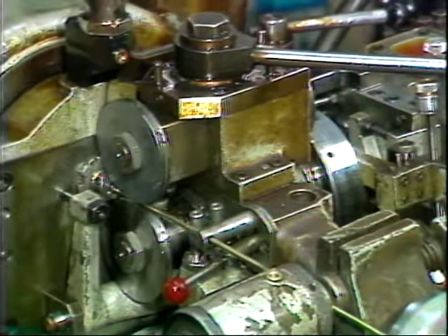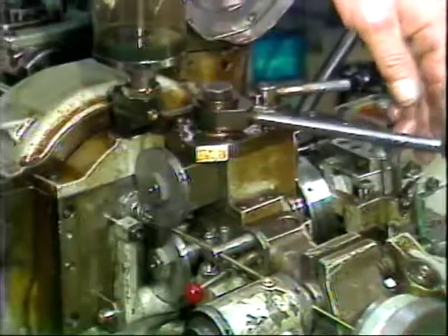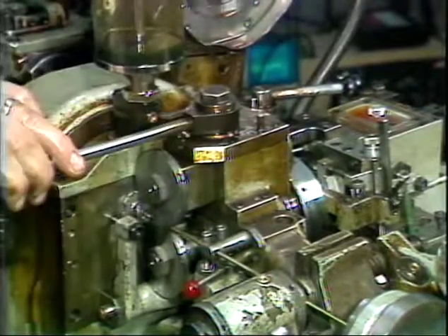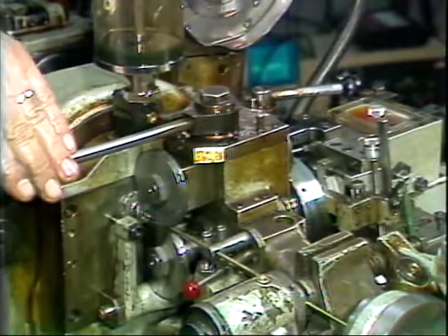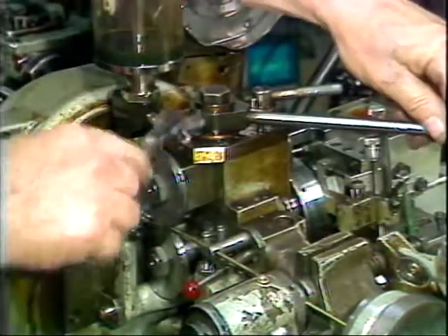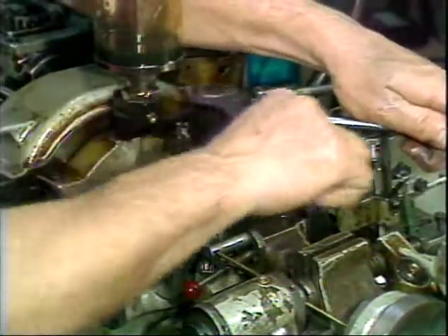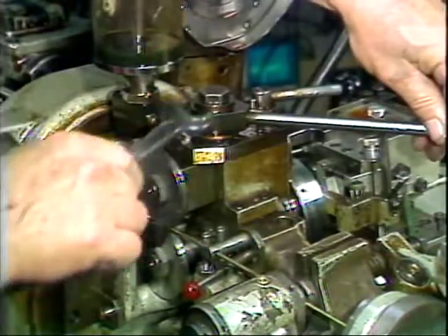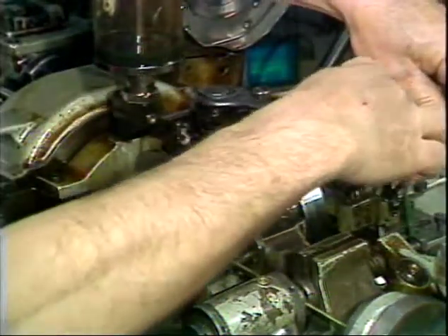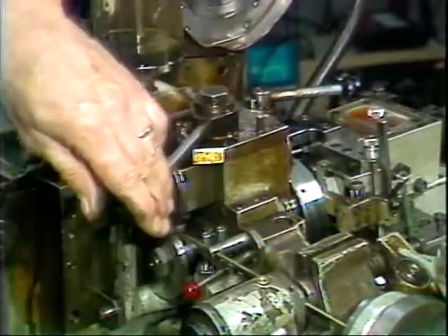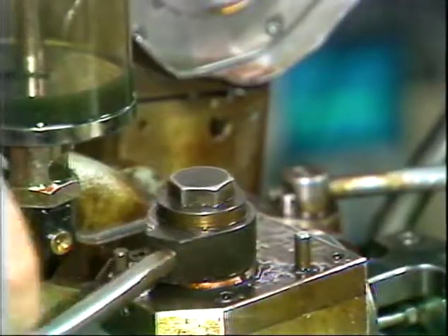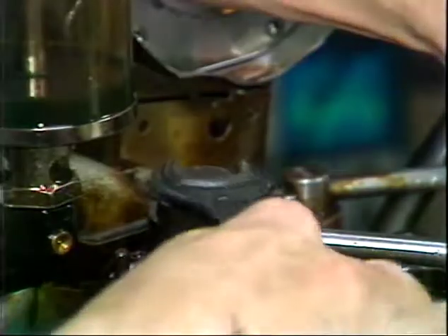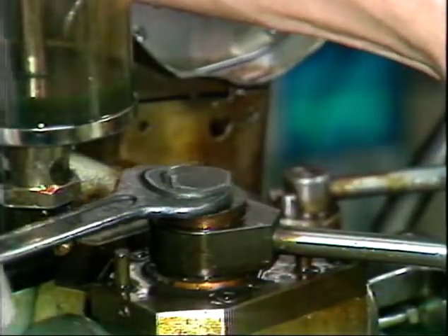Insert a piece of straightened stock of the proper size into the stock feed rolls and into the tooling area. Try clamping the stock using the stock clamp lever. Notice the point where the pressure starts to increase as you clamp the stock. Turn the pressure adjusting screw counterclockwise to decrease the clamping pressure. Turn the pressure adjusting screw clockwise to increase the clamping pressure.